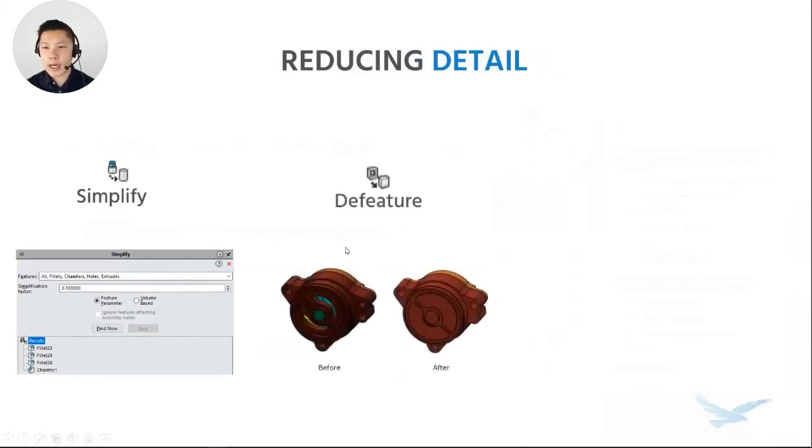If you want to go another way to do this, you can use Defeature. So with Defeature, you can simplify geometry as well as do a silhouette option. So with your simplify, it removes selected components and then geometry details, right? And then the silhouette, it's going to utilize the silhouette outlines of your assembly or your part, right? To create the defeatured component. In 2021, you can now save that resulting defeatured file as a configuration.